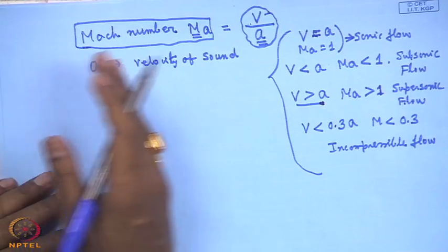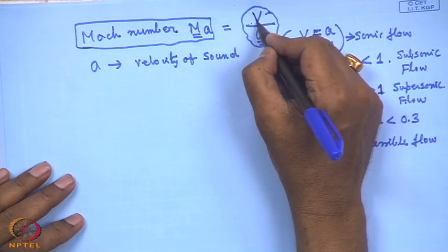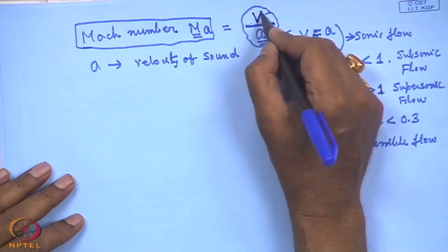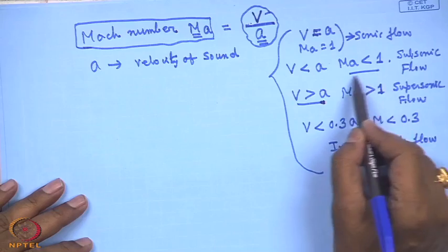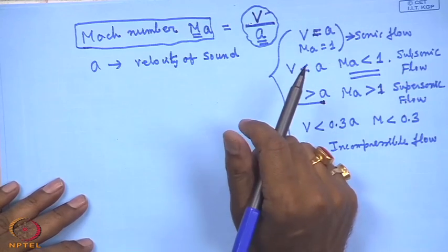Therefore, at each and every section of the compressor, the Mach number has to be considered. In the definition of Mach number, the velocity of flow is the velocity relative to the moving solid surface. When there is a flow past a solid surface, it is the velocity relative to the solid surface, and in turbomachines the solid surfaces are also moving. So the relative velocity of the fluid has to be considered in defining the Mach number, which has to be less than 1 to make the flow subsonic and avoid excess losses.